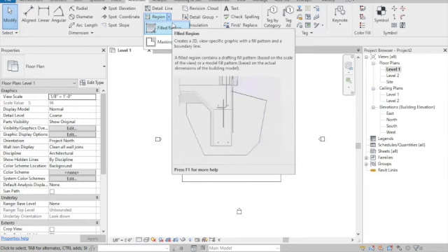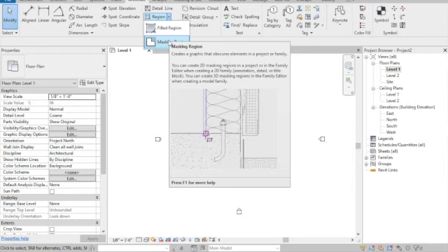Fill regions can be made transparent or opaque. Masking regions are multi-line shapes comprised of lines and a flat, opaque plane. The mechanics of drawing each of these are the same, so let's select Filled Region in the drop-down menu.